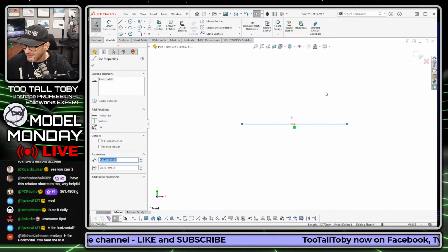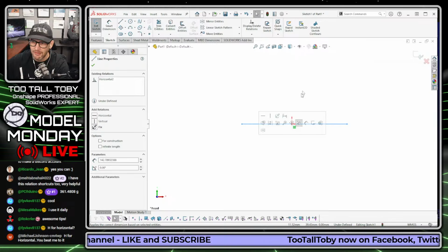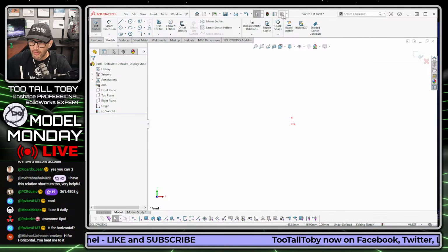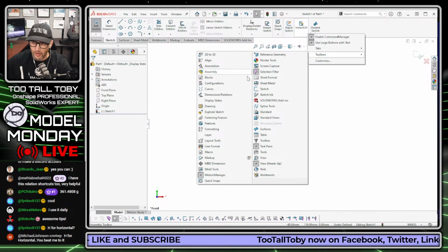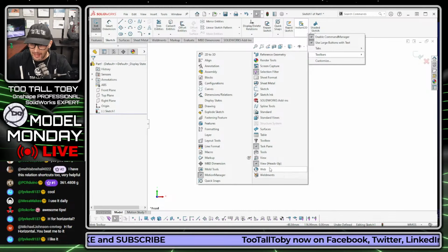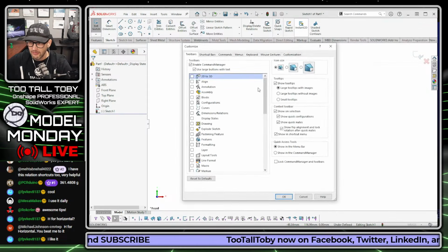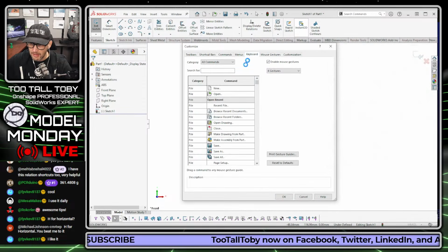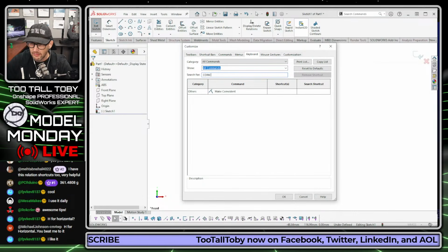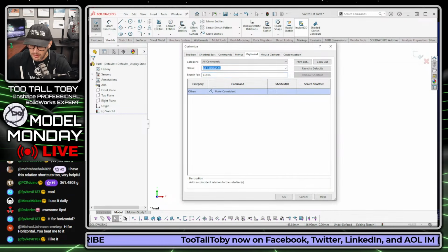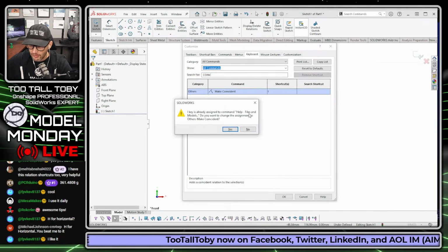So yeah, it's awesome. You can add relationships. I'm sure there are other ones you can add too, like coincident. In Onshape, coincident is I. So let's see, if we go here to customize, can we make coincident I? Let's see, Make Coincident. There it is. So we could just make that I. Okay, I is already hooked to something, Help Files and Models.